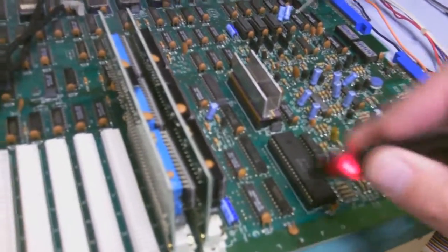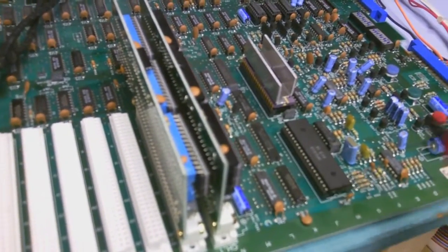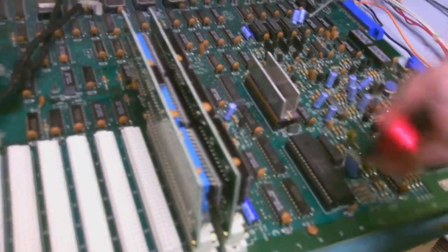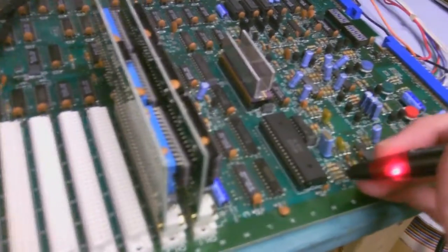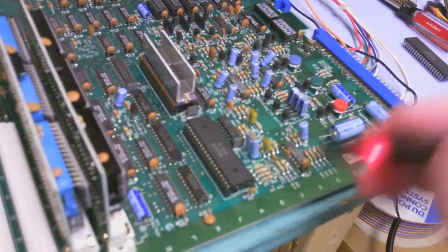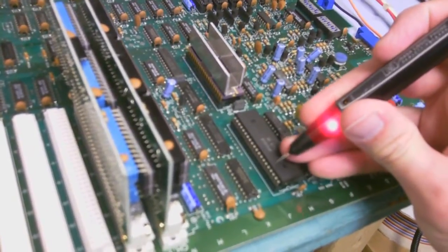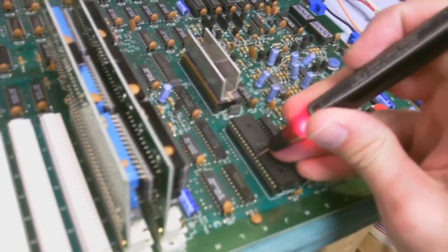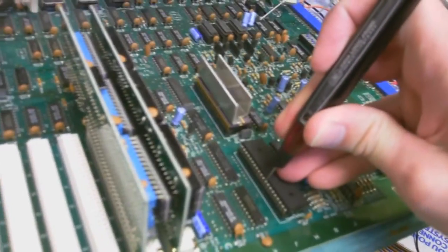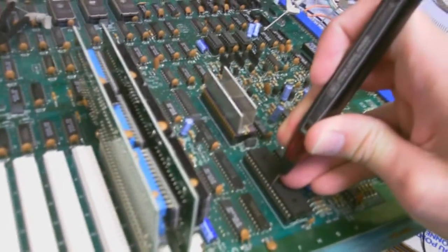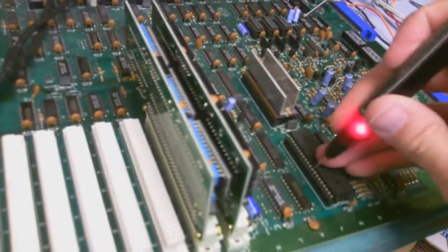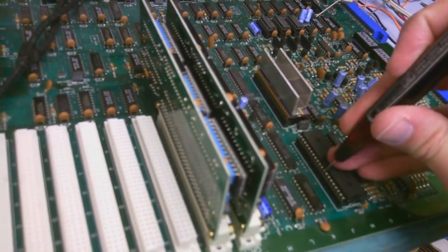So I'm starting to probe around this guy here, and sure enough I'm seeing something that's a little off. There's an IRQ input to this guy, which basically tells the CPU to handle an interrupt. And I believe it's pin 32, so let's count back: 40, 39, 38, 37, 36, 35, 34, 33, 32, and that guy is pulled low all the time. And it should be periodically pulsing low, but this guy's pulled low all the time.